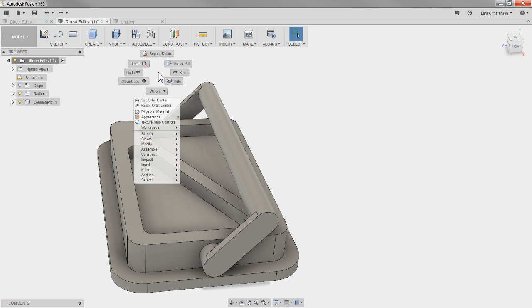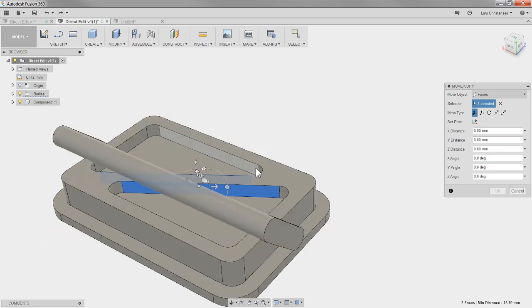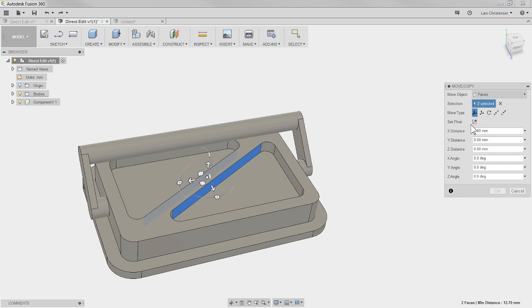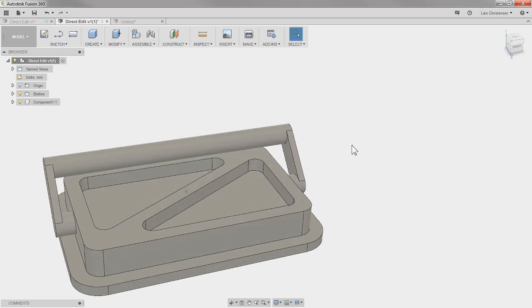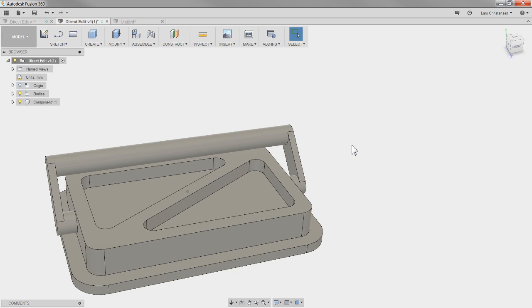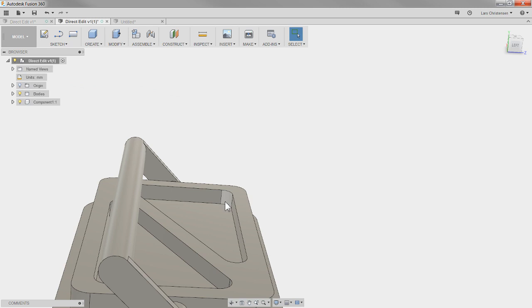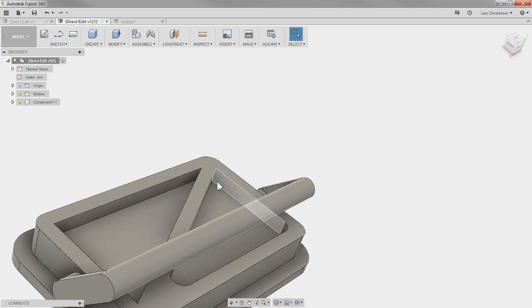So even if I did go in here and right click and say I'm just going to move these two walls here, let's see what happens. If I place this here, see how it will move that wall and it will adjust the fillets. It's pretty awesome that it will do that, but I would actually recommend, it can get a little hairy because the software has to calculate all those. Don't be shy to delete all those out of there first. I think that's a good practice. You can always reinsert them again, even in here in the direct mode.